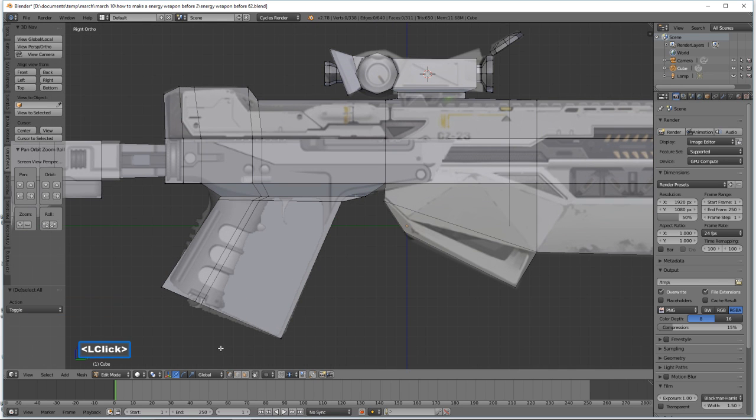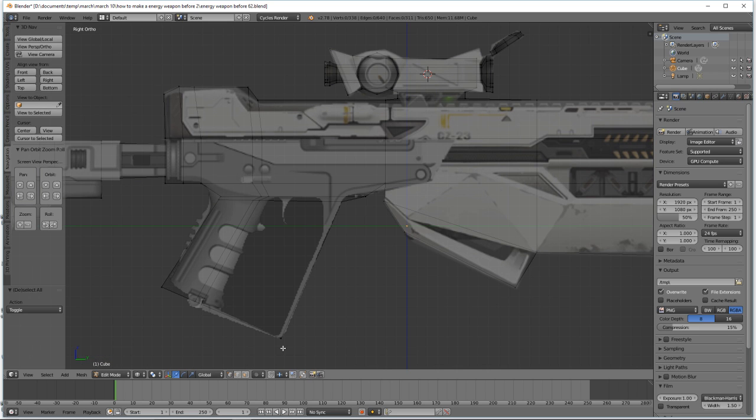I'm going to click here to go to vertices select. I'm going to press Z, then click here to go to wireframe view. I'm going to click here, grab these vertices here, push this down like that. I'm going to press A to deselect, press B for box select, grab right here. The reason why I'm doing that is because this is pretty thin right here, so I wanted to make sure that we had this in.